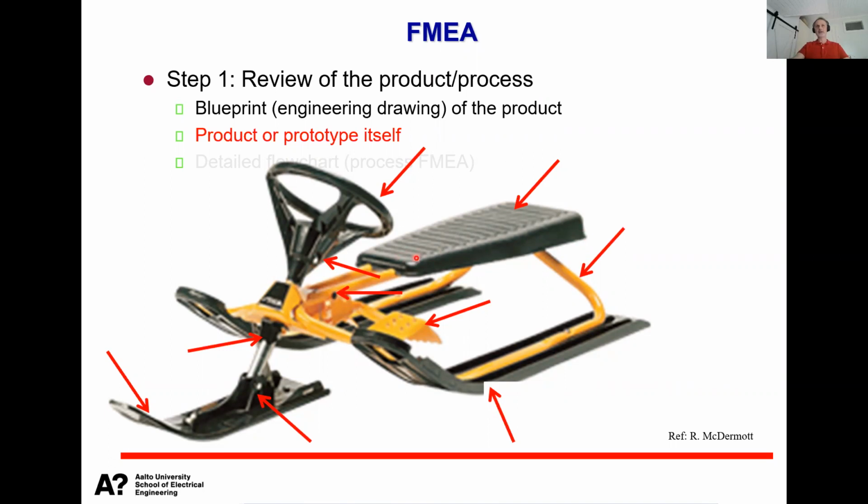On the other hand, you have here the seat, which maybe the reliability may not be that high. It's not mechanically very robust, and depending on how you store it, if you have this one the whole year in the sunlight, UV radiation really quite fast, maybe within a few years, will start to decompose the organic polymer material which is here.